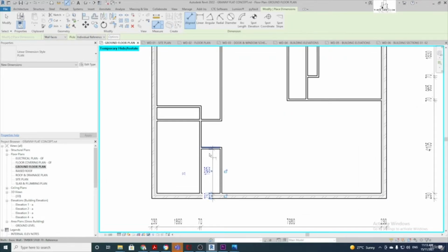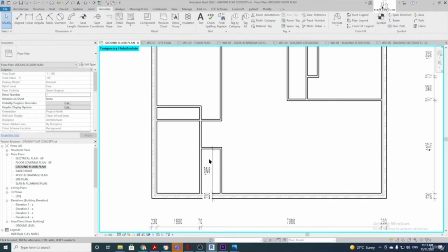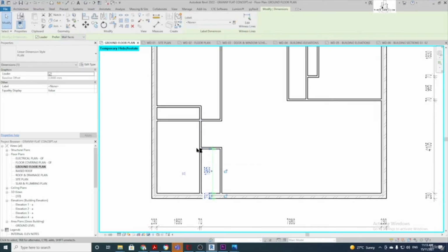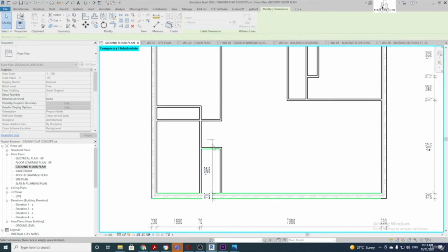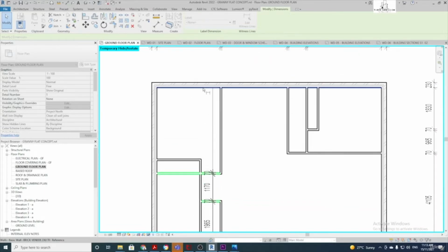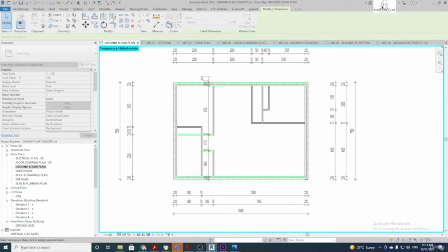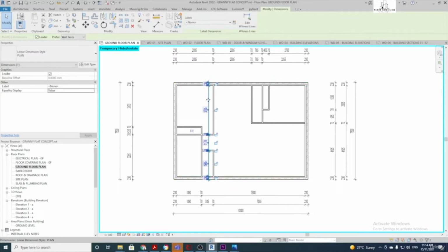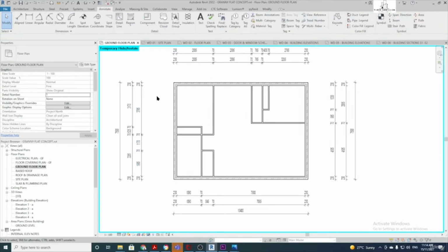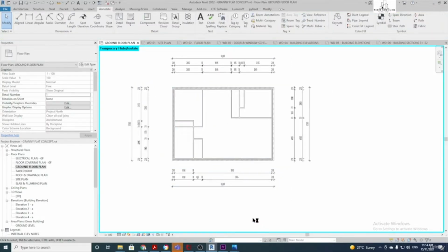If you accidentally click the wrong spot and you lose the dimension chain, you can click on the dimension like this. Up the top here it says edit witness line, click on that, then you can keep on adding back to that same dimension row, because that'll happen every now and then when you click the wrong things. And once you finish dimensioning, you click anywhere on the screen, then you can just grab it and pull it out again, like that. Now we've got our building pretty much dimensioned.